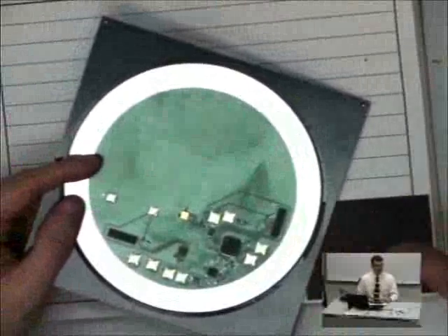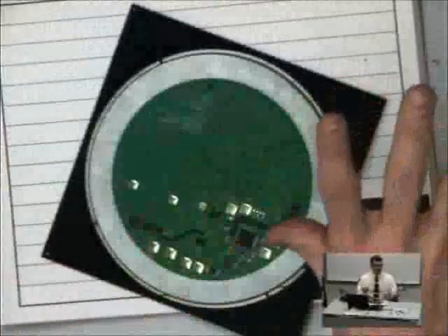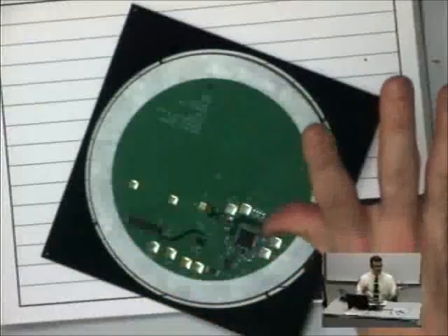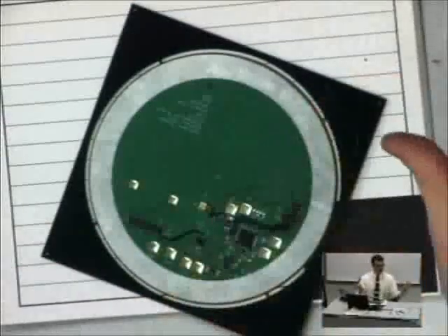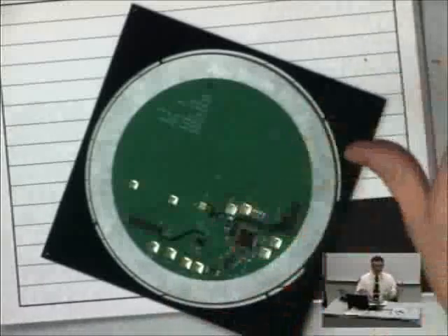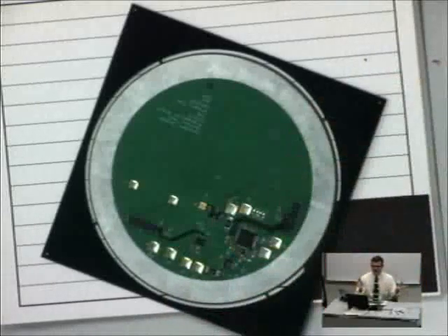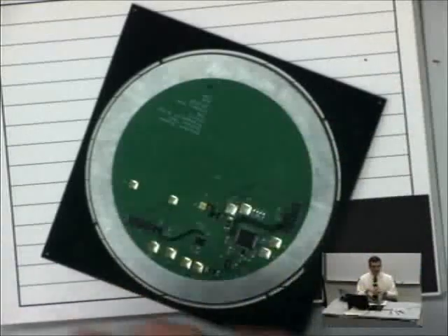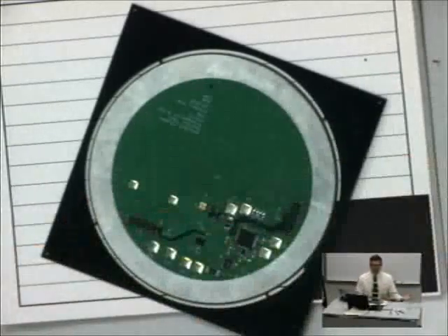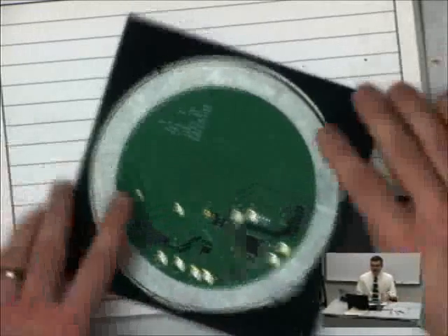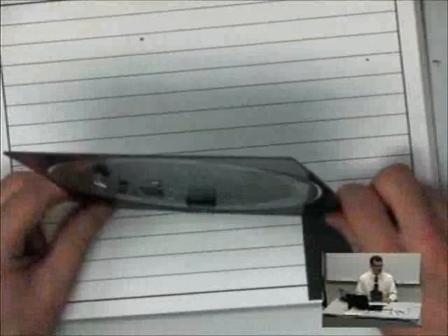This way you don't have any people or any stuff in the insulation gap of a high voltage line, because you can't put anything there. No metal, no dielectric, not even air. We kind of wish we could evacuate it because air is a lousy insulator, it turns out. But we can at least put some space there because air is free. And it has to be very low power because nobody wants to change batteries on a high voltage line. Spec is that this thing has to last 50 years in the field without a drop of maintenance. I'll pass this around so you can see the antenna, and the little gold switch on the backside is the load modulator, just like we discussed in class last period.